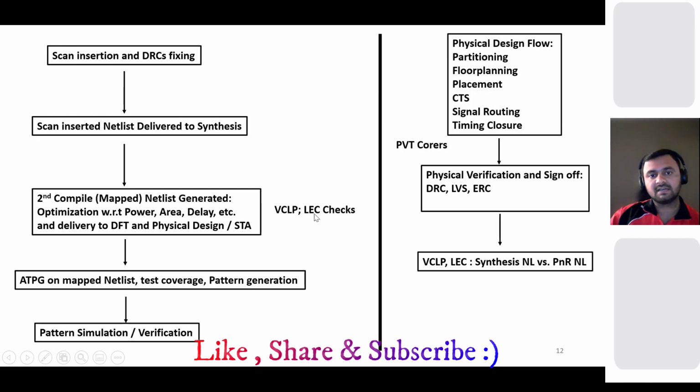Remember, this VCLP and LEC will be checked every time your design gets changed. So if you have changed your design, like inserting the scan, then again you have to check that your functionality should not change and that there is no power related issue.